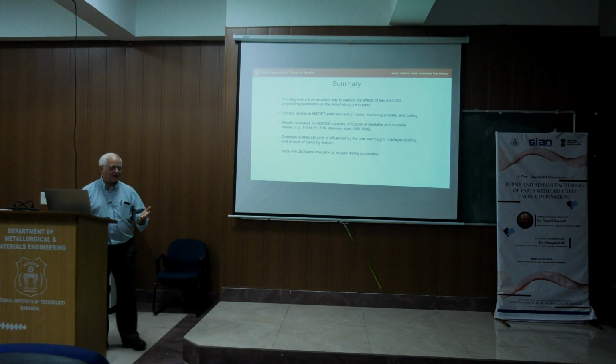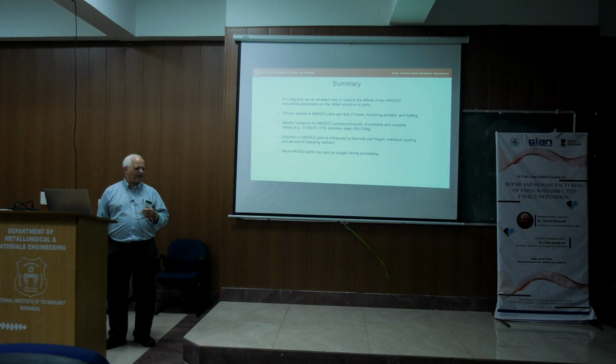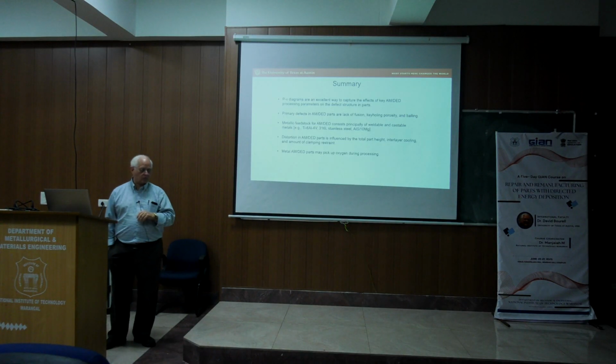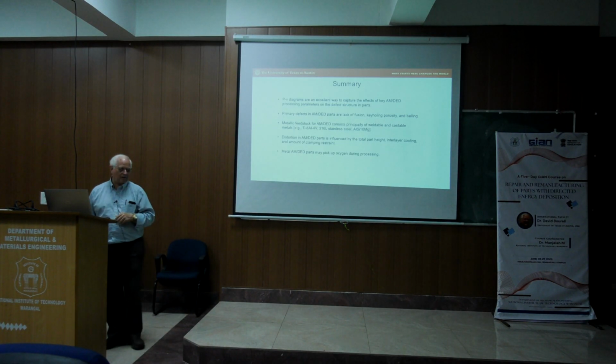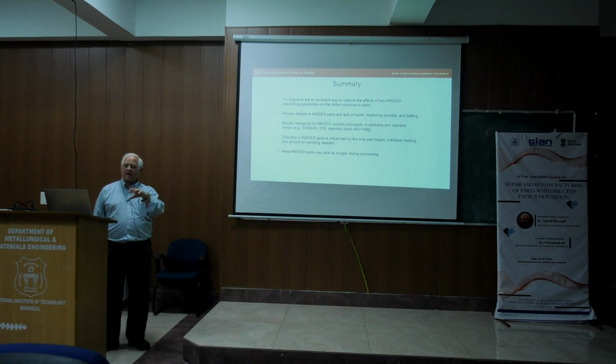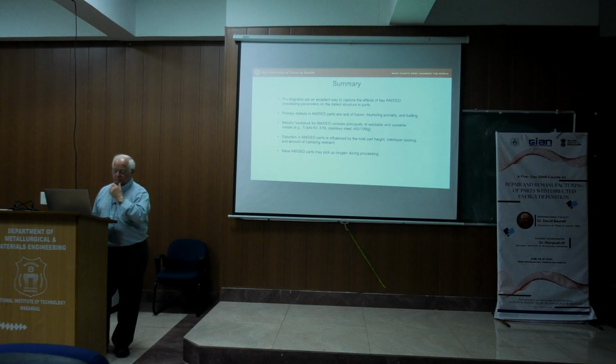As I mentioned on Monday, as we try to dial in new materials, producing the PV plots, which is what I did with the aluminum powder that I showed on the PV plot, is a great way to explore that space, and it can be done relatively quickly. The way we can do it quickly is we can build a variety of samples in one build by adjusting the energy source power and the scan speed. Those we typically do on the fly with these metal processes.